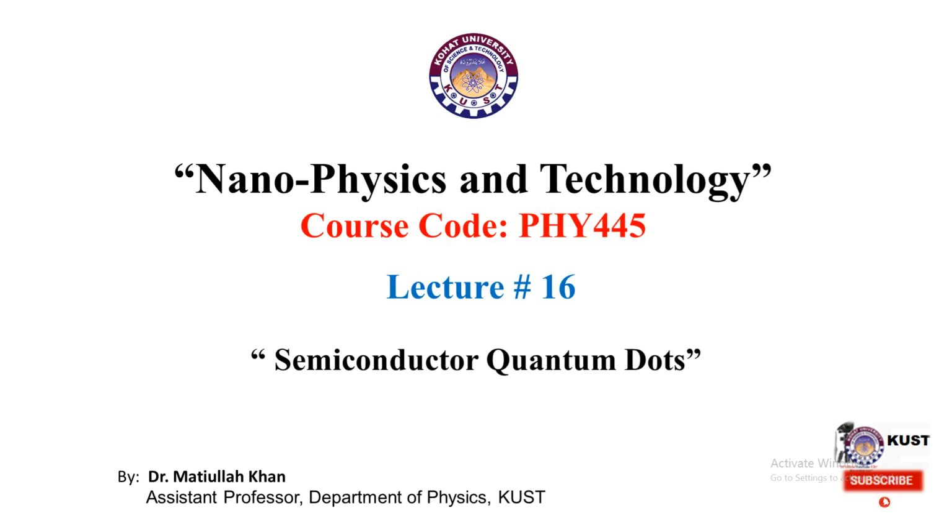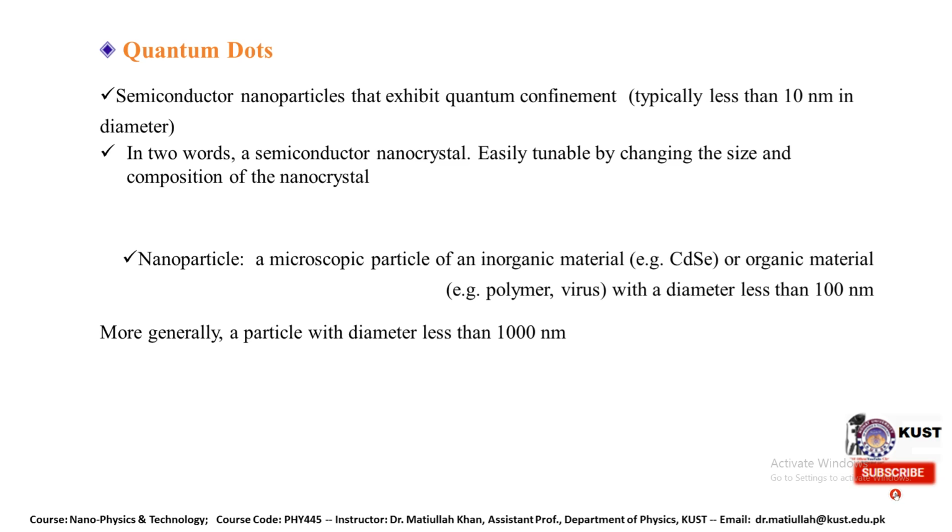Basically, in this lecture, we will discuss the synthesis, fabrication, properties and application of quantum dots. First, we need to know what is a quantum dot. So this is very important to us. A semiconductor nanoparticle that exhibits quantum confinement, and its size is typically less than 10 nanometer in diameter. So those are actually quantum dots.